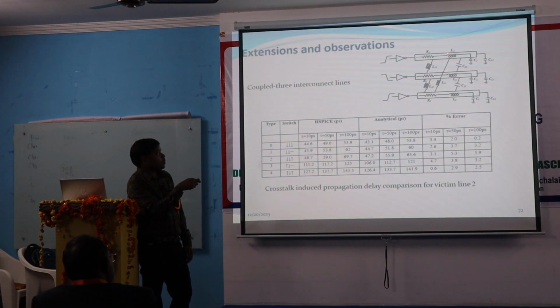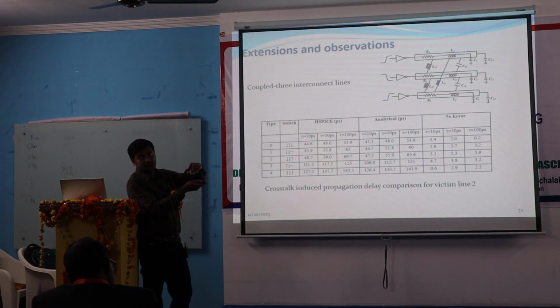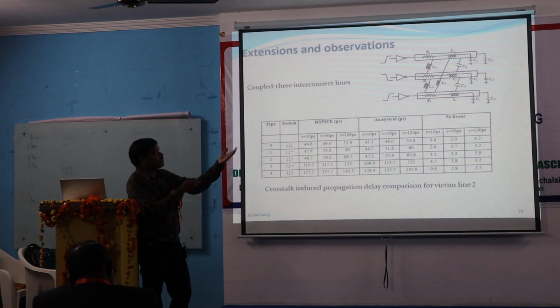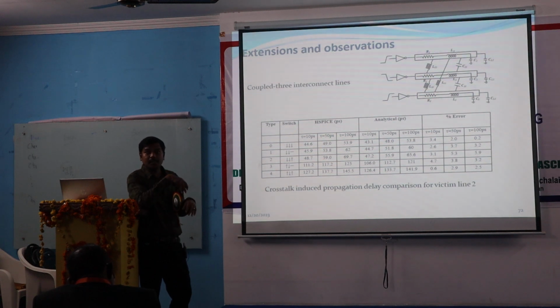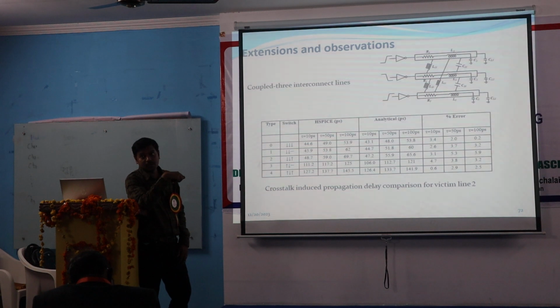In this case, 1 will not see interconnect 3 because 2 is acting as a shield. It is completely covering. That interconnect 2 will completely cover L3, right? It cannot see L3. 1 will not see 3 in terms of electric field coupling. But 1 will feel the 3 in terms of magnetic field coupling. So that's why you should place L13 also.